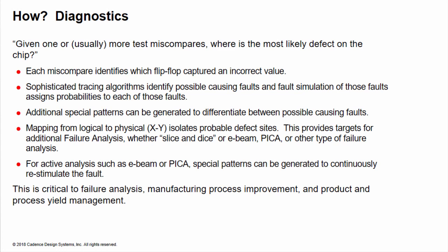Once the most probable logic faults are called out, they may be mapped onto an image of the chip, mapping the fault information from the logical to the physical domains. This provides a starting point or points for the failure analysis team to start investigating. Optical inspection of the identified area is a frequent first step, as many defects of the wiring will be visible.